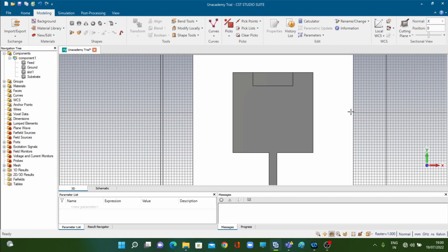This is the same as mathematical addition. Whether you add 3 to 6 or 6 to 3, you are bound to get 9 only in the answer. Same thing is happening here. But in case of subtraction, it is not like that. Mathematically, if you subtract 3 from 6, you will get 3 only. But if you subtract 6 from 3, you will get negative 3. Now in mathematics, getting a negative difference is allowed. You can actually get it. But in this Boolean subtraction operation in design, a negative difference is not allowed. You will get an error.